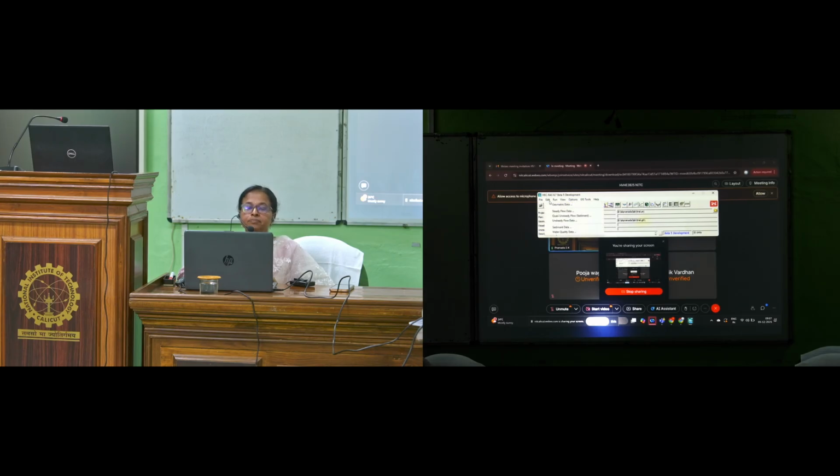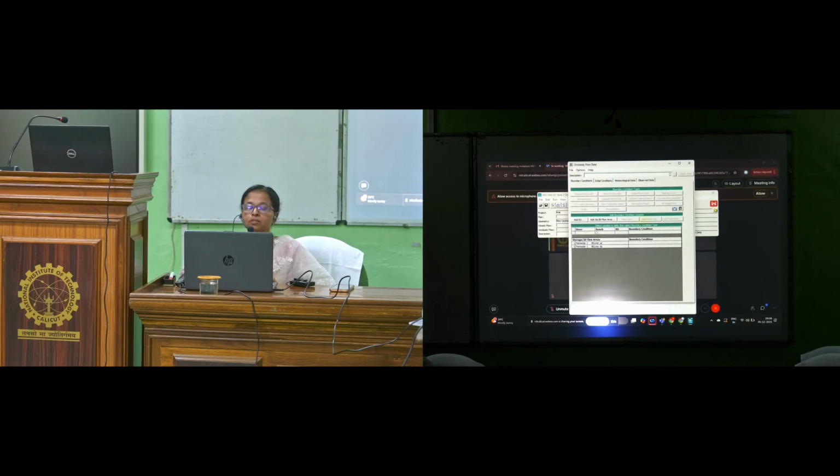Then edit. You have to give the flow details, unsteady flow data. Here you have to give the values for boundaries. Now we have created only the lines to identify the boundary conditions. So here upstream. This flow hydrograph you have to take from the hydrologic model. Usually people will give, for a particular rainfall, the corresponding outflow hydrograph. So now I am going to give an event for a particular rainfall event.